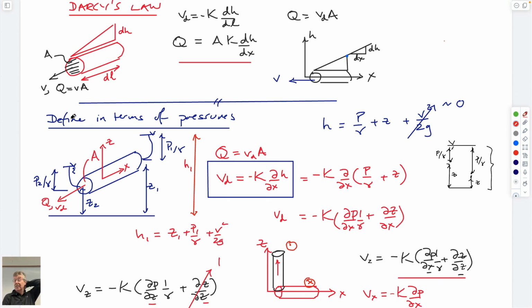So the idea is that you've seen Darcy's law in 452. You know that it relates to maybe flow within a core, and you know that it defines a Darcy velocity here as the product of a hydraulic conductivity and a head gradient over length. The length of this core that's filled with porous media is this. I guess you could define that as two components, which are Z and P over gamma water. I guess this could be 1 and 1. And if this is coming out at atmospheric pressure, which I guess this would suggest, the pressure here is 0, then this would be Z2.